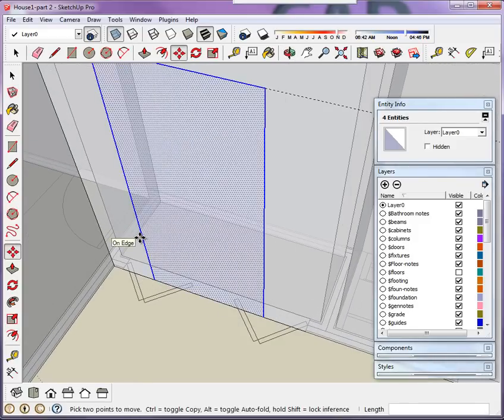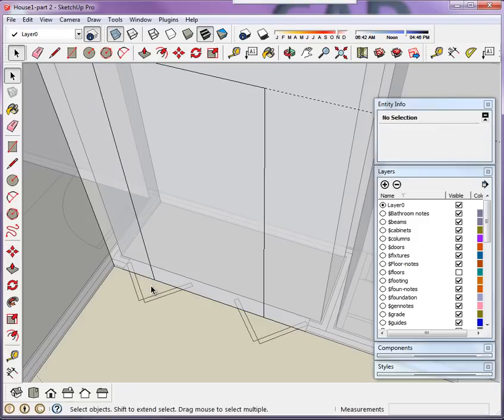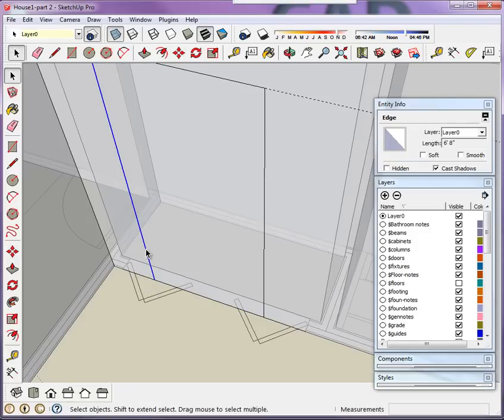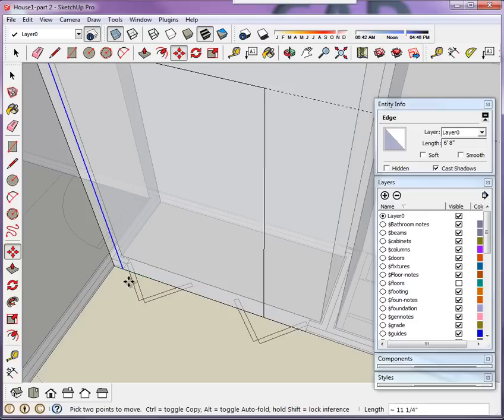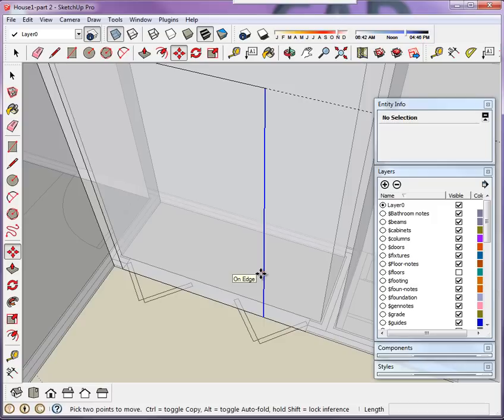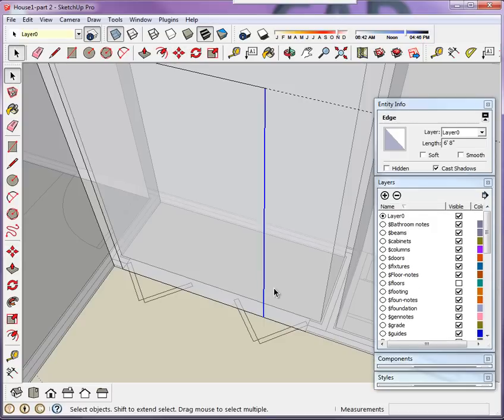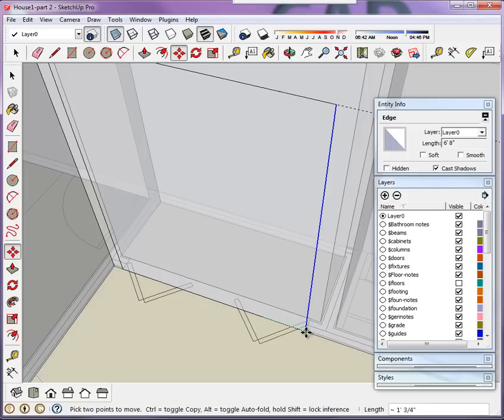Just put it in there. Now look at this. I'll leave it right there, go back to selection mode, Control T to deselect. Select the edge here, type M, and now you can move. Snap to one side, Control T to deselect, spacebar to select, then left click to select the line and use M again to move it.